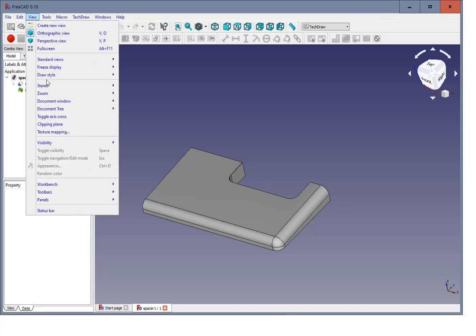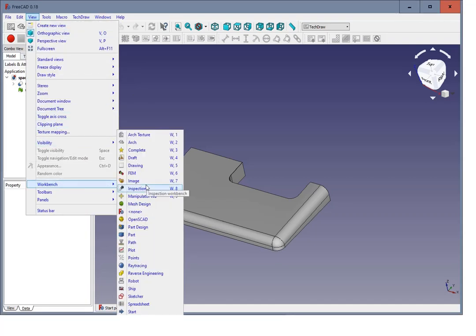So we change the workbench to one I've not shown in my videos before, the technical drawing workbench, the TechDraw. Don't think that this is a workbench where you create something. You must have created something before in any other workbench that is a visible object inside of your design, and then you just create a technical drawing out of these objects.